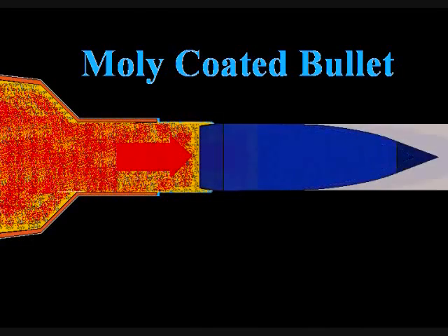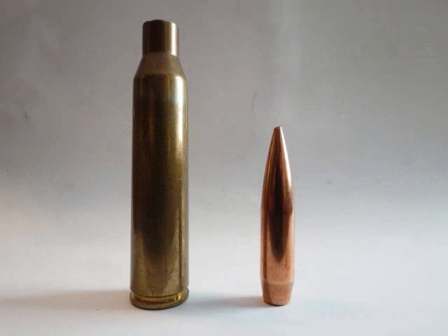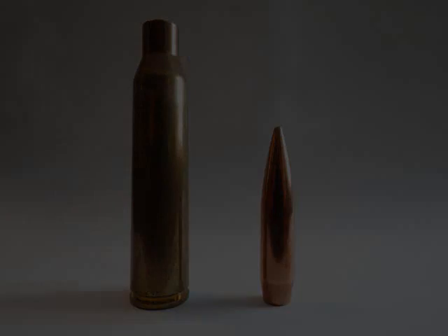So coppering is real simple. Basically, as you fire your projectile, the heat and friction cause a thin film of copper to deposit in the bore. When you get a brand new rifle and start shooting it, you're going to deposit a film of copper, and then you take the next shot and it deposits some more copper, and you take the next shot, and it's just going to keep adding on to that amount of copper until you reach an equilibrium point.